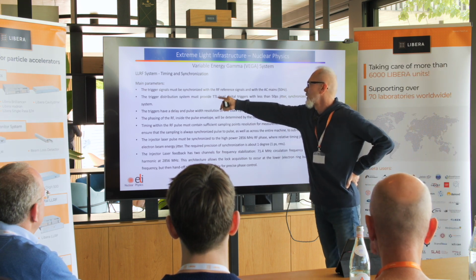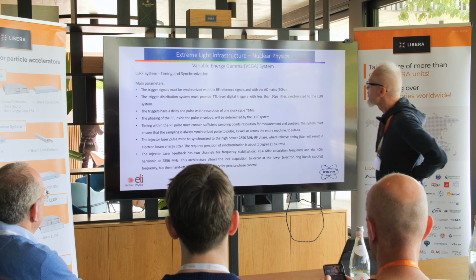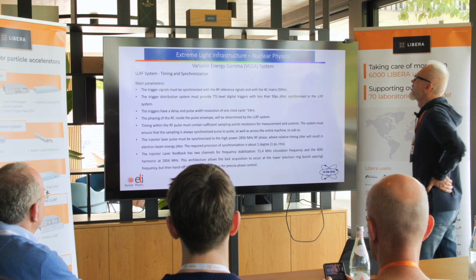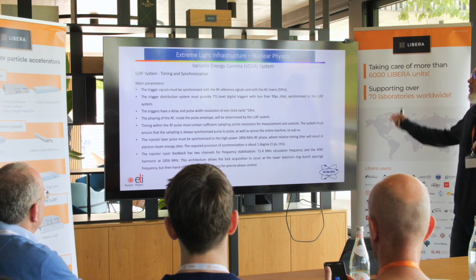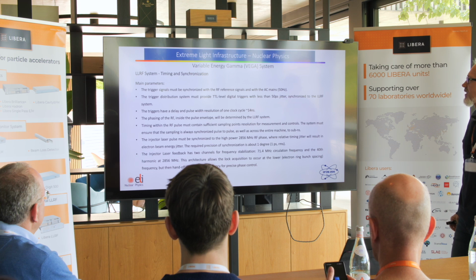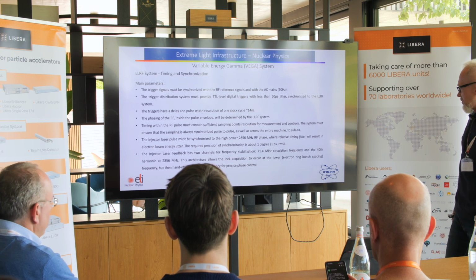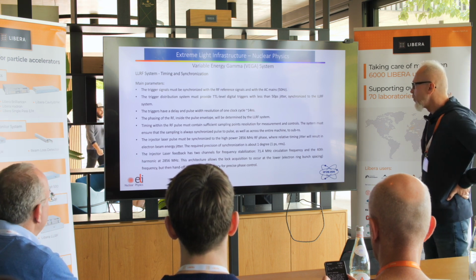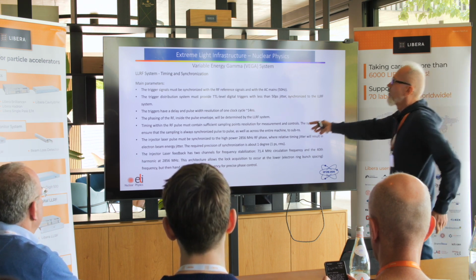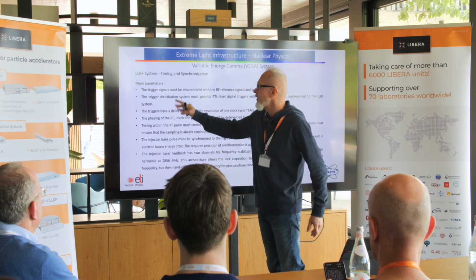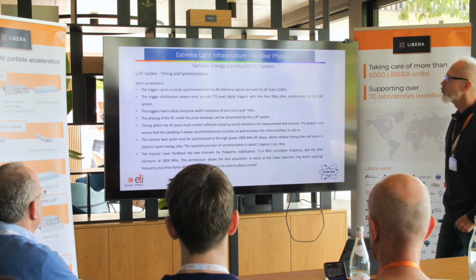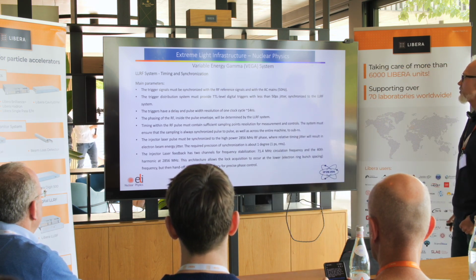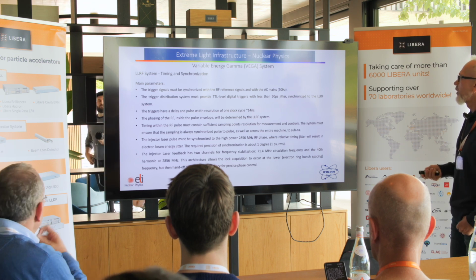And we need to provide transistor-to-transistor logic level digital triggers with jitter less than 50 picoseconds in order to synchronize the low-level RF system. Okay, about the delay pulse, I don't need to insist so much. And also, all this information is related to the phasing, energy, and amplitude of the signals which will be generated in order to control the whole equipment.